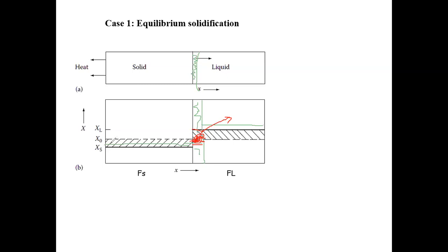Okay, so that it eventually reaches the equilibrium composition of solid, and that composition equals whatever composition is required by this temperature. And for a similar process, during the solidification of the thin slab, you repel a lot of solutes, an extra amount of solutes, into the liquid, and these extra solutes also quickly redistribute themselves into a uniform distribution in the liquid, because the diffusion is faster there.